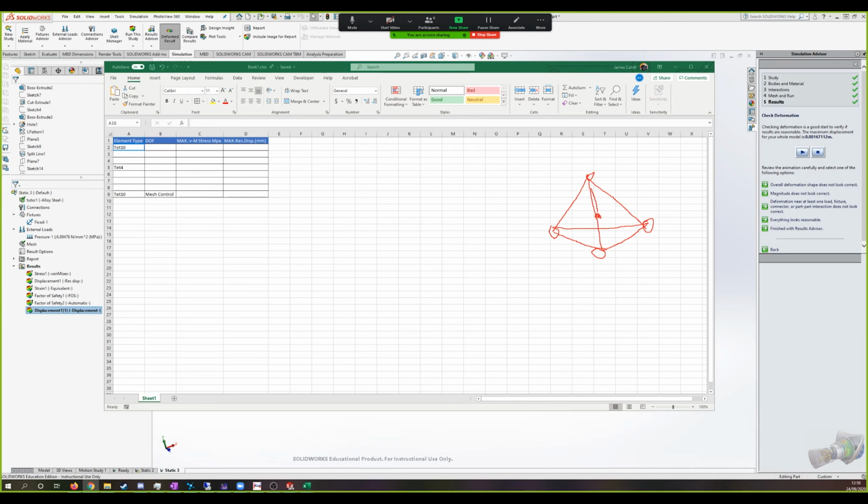Now, because you've only got 2 points, to calculate the displacement of these 2 points is a linear equation, right? Like 2 vertices, say this one and this one. You've got 2 vertices, so it's a linear equation between the two. Tet 10 has 1, 2, 3, 4, 5, 6, 7, 8, 9, 10. It's got one halfway along each edge. Which means if you've got 1 point here, 1 point here, and 1 point here. Yeah? I'm lost.